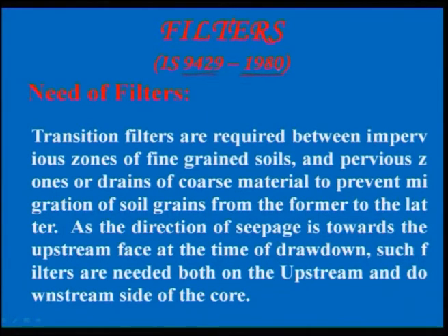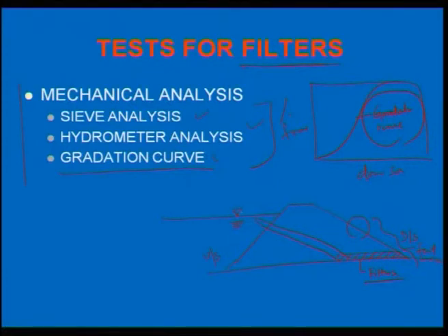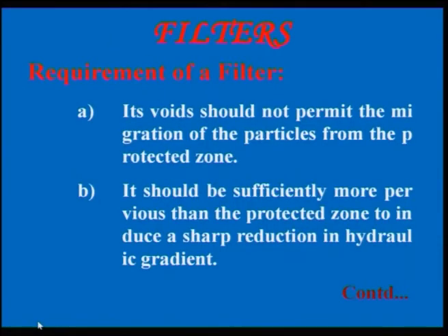Look at the meaning: the moment a filter has been applied, it only allows water to pass, remember it, it only allows water to pass, it does not allow soil to pass along with water. The moment soil flow, meaning water flow, starts inside the body of the dam, what will happen? Soil plus water will flow inside. So, here soil will be filtered and water will pass inside. Next class we will discuss the complete design of this filter material and what the test requirements are.